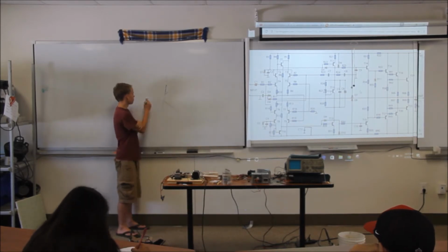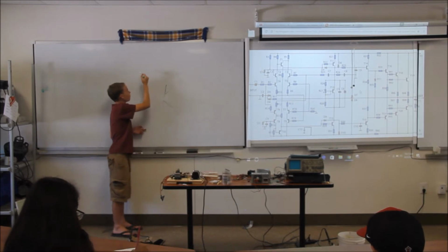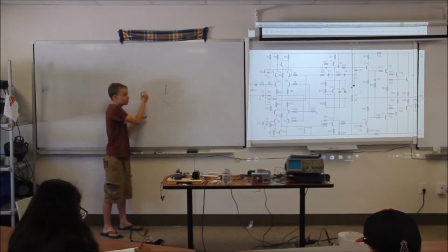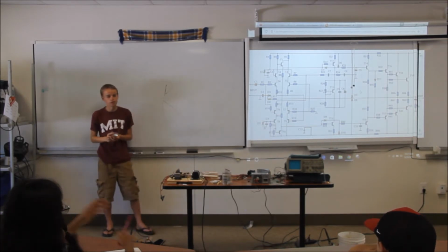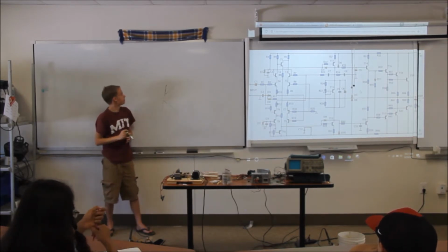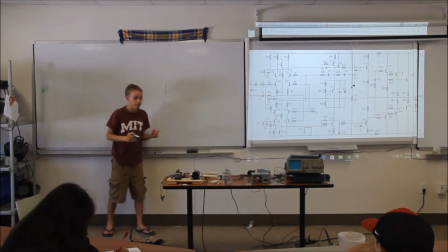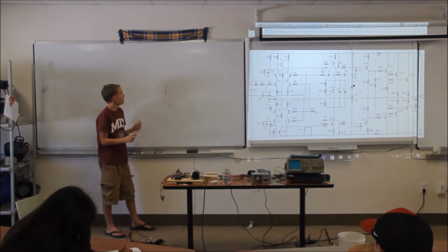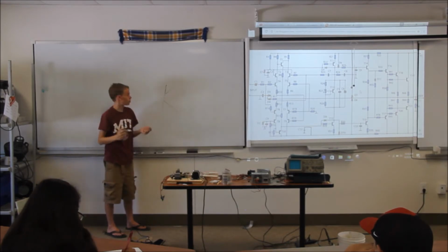So if you turn on the base and you have a switch, then you'll have the current flowing from positive, which is up here, and let's say that's 5 volts. And you want to put a resistor on that voltage, because if the voltage exceeds a certain current flow through the transistor, you'll blow out the base. So we'll have to put a big resistor on there that goes to the base. So that slows down the current going into the base, so that it's not too high.